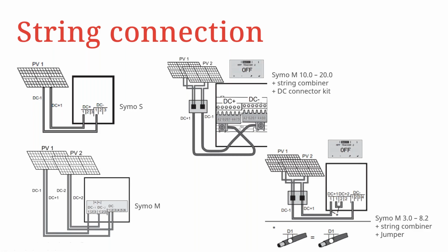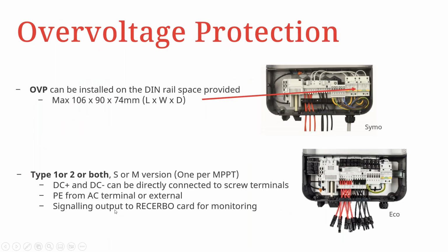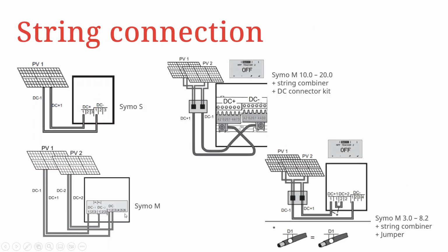This is due to the positive side having a separate bus bar on the multi-string design, but on the neutral side, they all share a common neutral. So it doesn't make that much of a difference, for example. If you've got, let's say, 3 and 4, and 3 and 4 are only on DC2, all the same orientation as PV2, they will then occupy 2 and 3, for example.